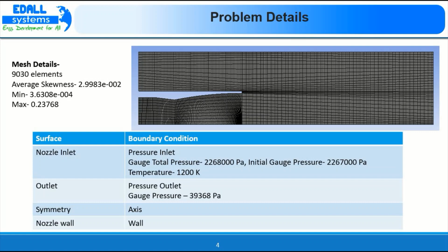For boundary conditions, for the nozzle inlet we'll be using a pressure inlet boundary condition, because here we have the data of the pressure values at which the propellants enter the nozzle region. Because we have temperature and pressure values, we could also calculate velocity values, but instead we can use these pressure values directly as a pressure inlet boundary condition and specify these properties there.